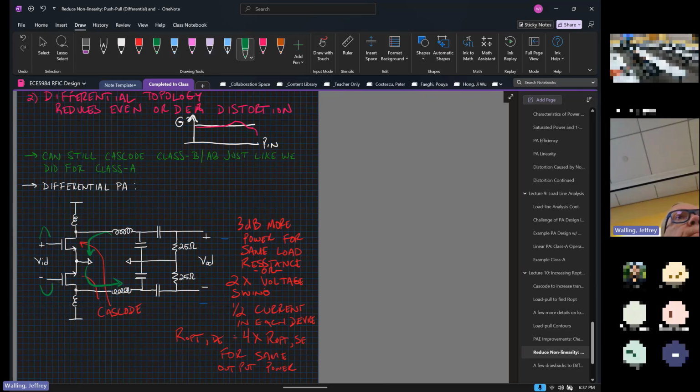Okay, but then what about when the other half of the sine wave? Yeah, same. Well, if I bias it as a class B amplifier, yeah, I can do it. I'm just looking at class A here, but yeah, we could do a class B amplifier. It's still a push pull. If I look at the harmonic content and the voltage waveforms, I'm still doing more or less the same thing. But you're right, it's not practically operating in the same way. But I would still say I'm driving one half of the circuit and not driving the other half of the circuit in that case.